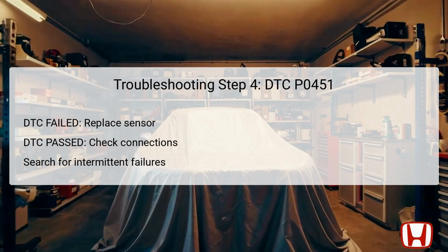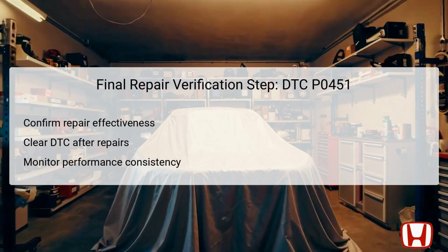Additionally, if an onboard snapshot of the DTC is recorded, attempt to replicate the failure under the same conditions. This deeper verification allows for identifying inconsistencies that may not be present during standard testing. After replacing the FTP sensor or addressing any connection issues, conduct a final repair verification.